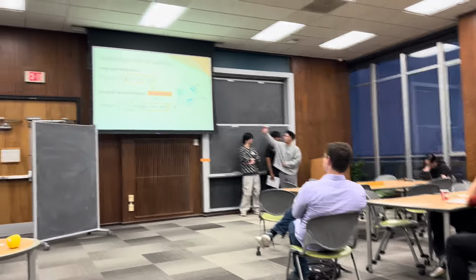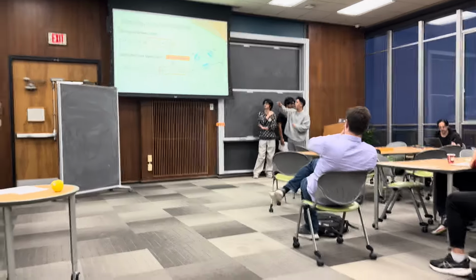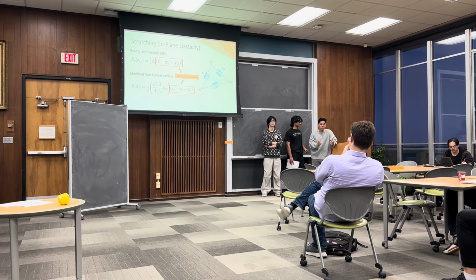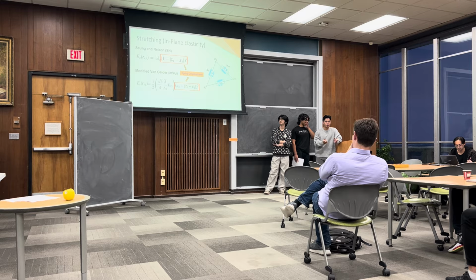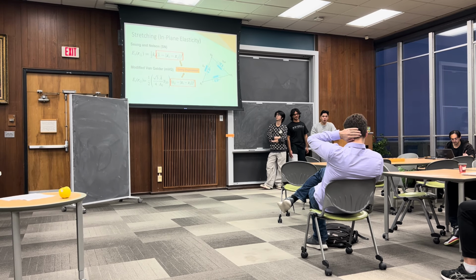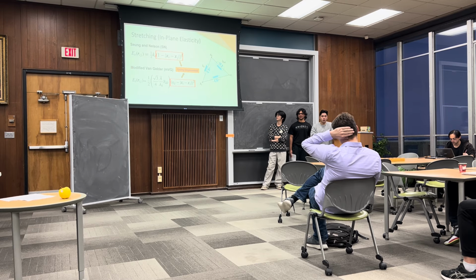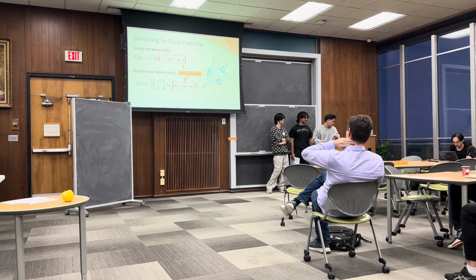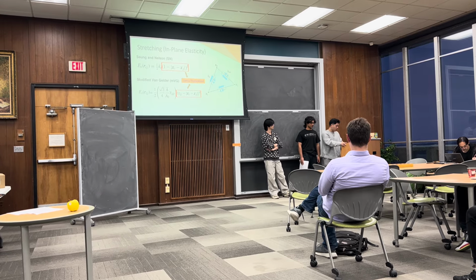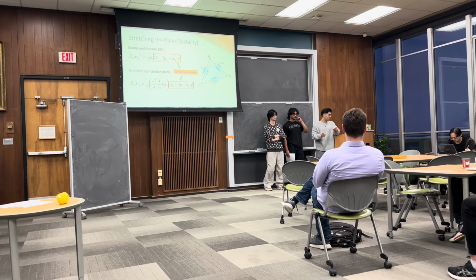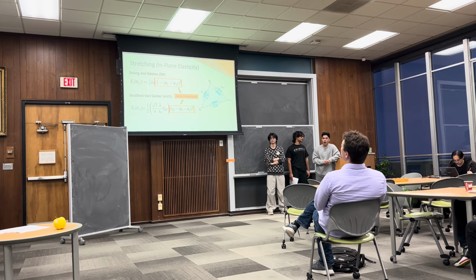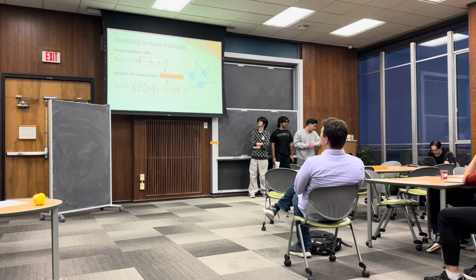As we can see in the Zhan and Nelson model, they apply 1 minus |xi minus xj| in the spring displacement because originally they treat every node spacing as 1, and xi minus xj is the location of the two nodes after the simulation. It's different in the modified Van Gelder model because they treat every node spacing differently, so we can see they use Sij instead of 1 as the displacement here.